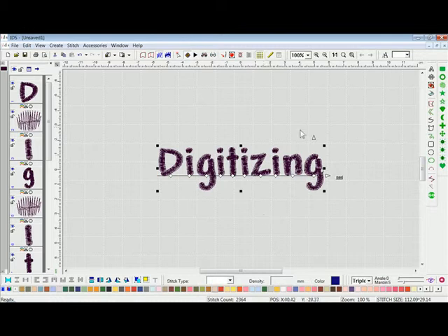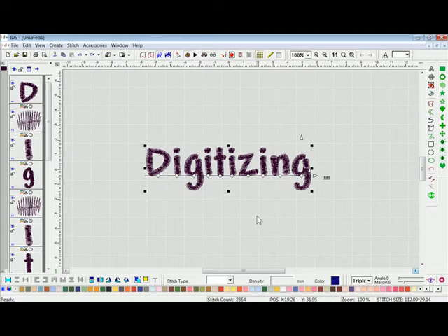We have 3 arrows on the right hand side of our lettering, as well as white diamonds underneath each letter. We also have an edit button directly to the right of the last letter. As you can see, our lettering is on a straight baseline, and our lettering does sit above the baseline. Our lettering is also automatically spaced, and that does indicate to me that it is on an automatic text path, meaning that it put it on the best fit straight line and did the spacing accordingly, according to the letters and the font. Now on the right hand side of our screen, we will first go over the arrows.